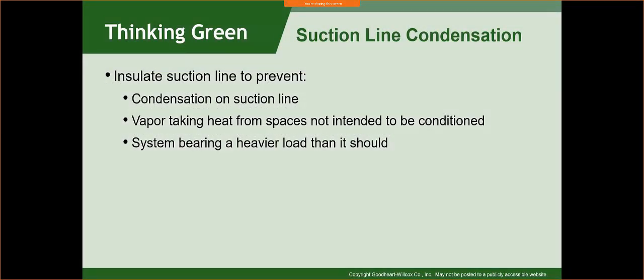So, think green, insulate suction line. We don't want any condensation on the suction line, vapor taking heat from spaces not intended to be conditioned, and the system bearing a heavier load than it should. All these things are true if we don't have insulation on there.